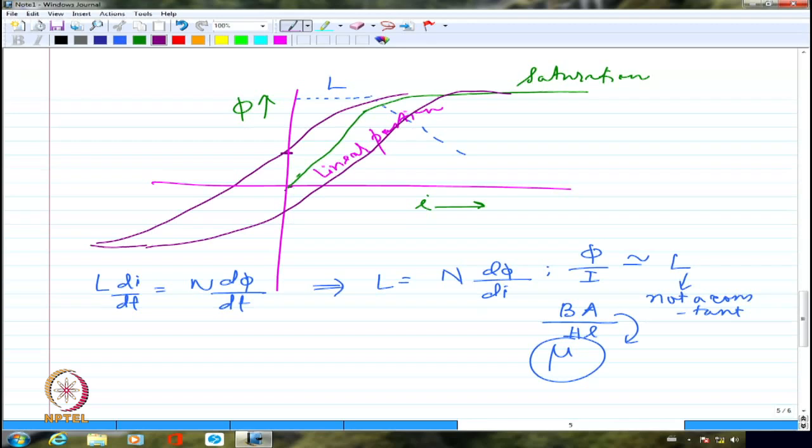especially if I want to use this transformer for measurement. Let's say I have 1000 amperes of current. I do have an ammeter only corresponding to 10 ampere. What I will do is to use a current transformer which will step down the current from 1000 ampere to 10 ampere. I can't assume that when I am actually coming to 10 ampere in the main winding, it will be really 10 divided by 100.